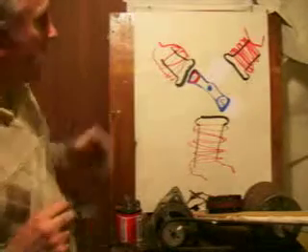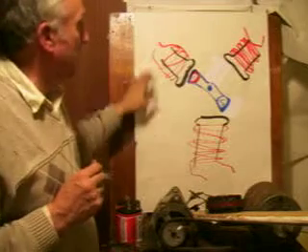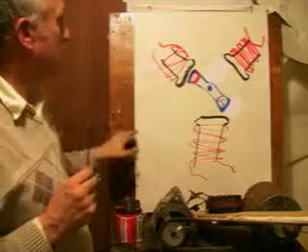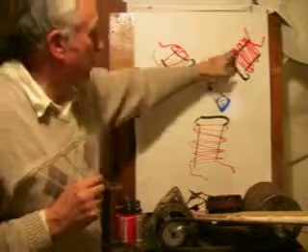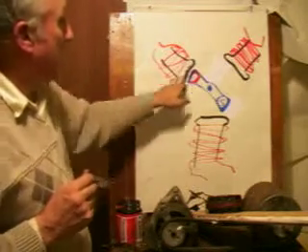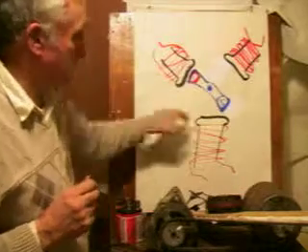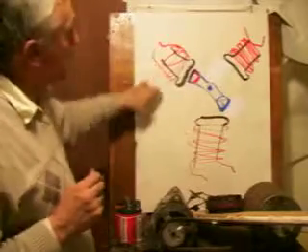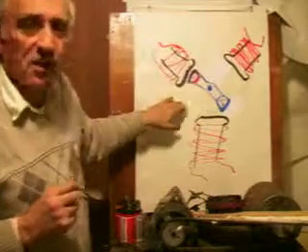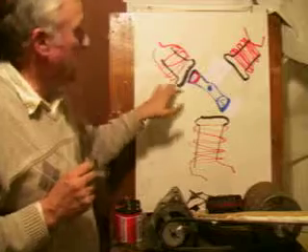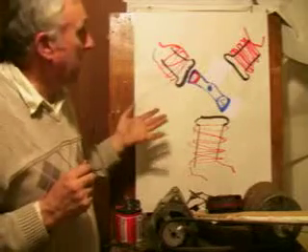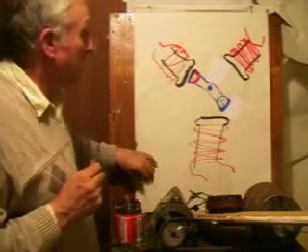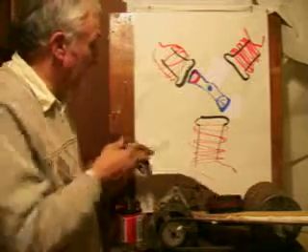So this is a look at the alternator for producing the AC 3-phase current. You have 1, 2, 3 coils, and you have the magnetic field going around. This creates a magnetic field which rotates, which appears to go round like that in a circle. Whereas the ordinary single phase machine produces just a simple phase which does not rotate. It's more or less stationary.